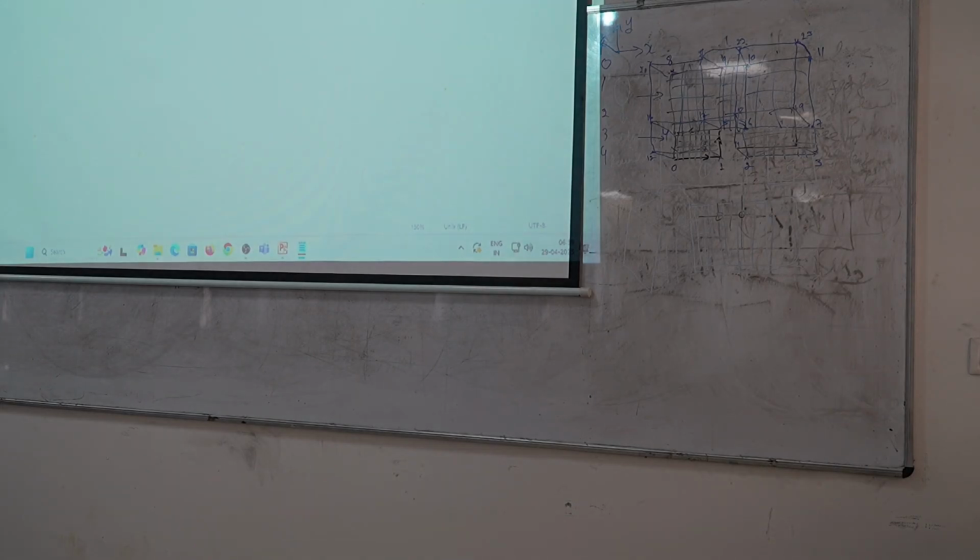Whenever we define these faces, we need to be very specific about the direction in which we are defining the vertices. Why? Because if I specify a vector quantity, then it has some direction along with the magnitude. So, the outward normal direction should be defined based on the orientation of the geometry, so that it can accordingly map to the velocity value specified in the boundary condition. That is why when defining a boundary, we need to judiciously specify the sequence of vertices.